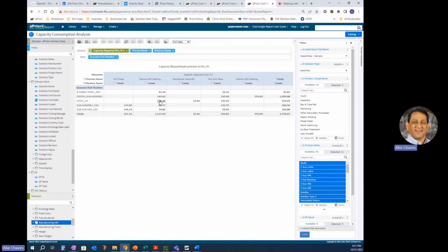And so you can see how these 3 assemblies here, especially the hitch that we were looking at, are consuming a significant amount of MIG welding. The hitch, unfortunately, has moving parts. And if you cast it, those parts ain't going anywhere. They're not moving. So that one is eliminated just from the point of view that you can't cast it. But the other 2 are definite candidates.